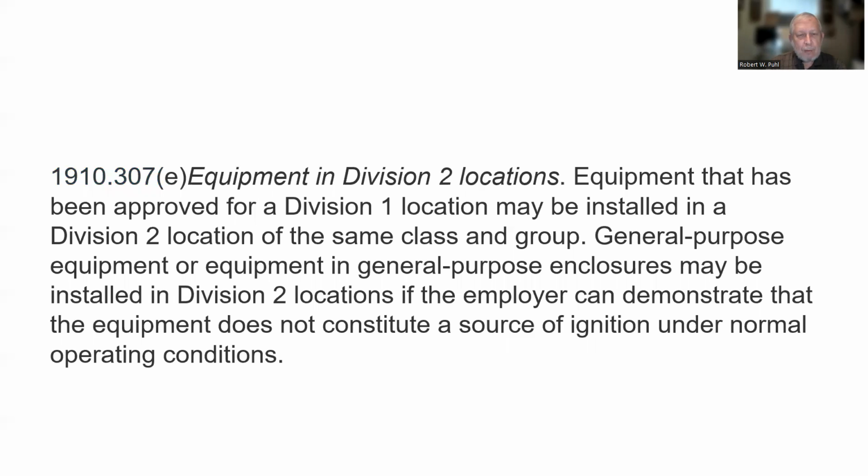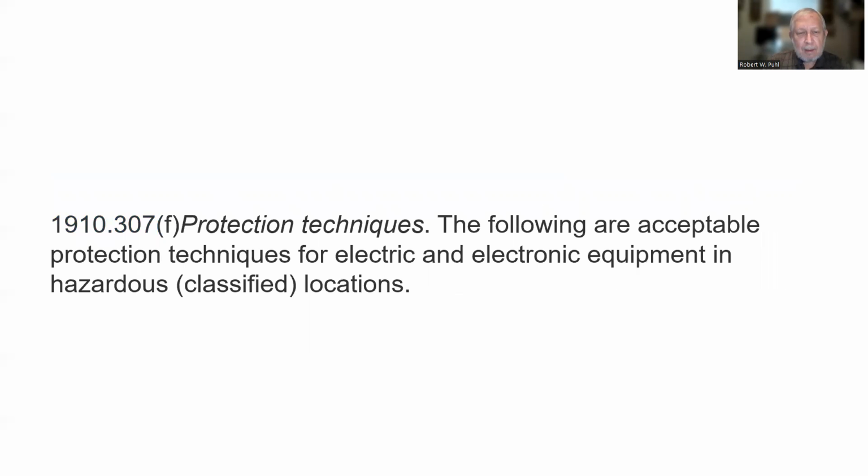Equipment in Division 2 locations. Equipment that has been approved for a Division 1 location may be installed in a Division 2 location of the same class and group. Okay, we don't know what they are yet, so that. Well, we're not going to cover all these details.